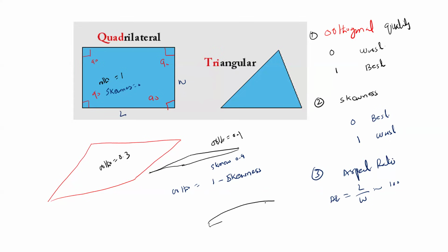So on the surface of an aerofoil, we can have large cells along the length of the aerofoil and very small cells along the normal to the aerofoil surface. And why is this so? Because the gradients change more normal to the aerofoil. The values change less along the chord length of the aerofoil compared to the normal direction. So that's why we can have large cells along the length of the aerofoil, but small cells normal to the aerofoil.